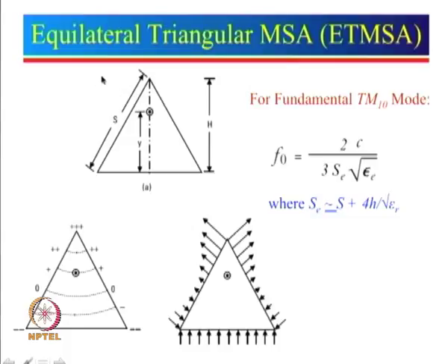So, over here now we know the field variation. Now, this I have shown in a slightly different way. Pluses here show that the field is going outside and then it is reducing. It is reducing, it becomes close to 0 here, and then minus sign means the field will be coming from the ground plane to the patch. So, it shows here. Similarly, the field is minus here. So, the field is coming from the ground to this. So, the component will be shown in this particular direction, and the same way it is shown over here.